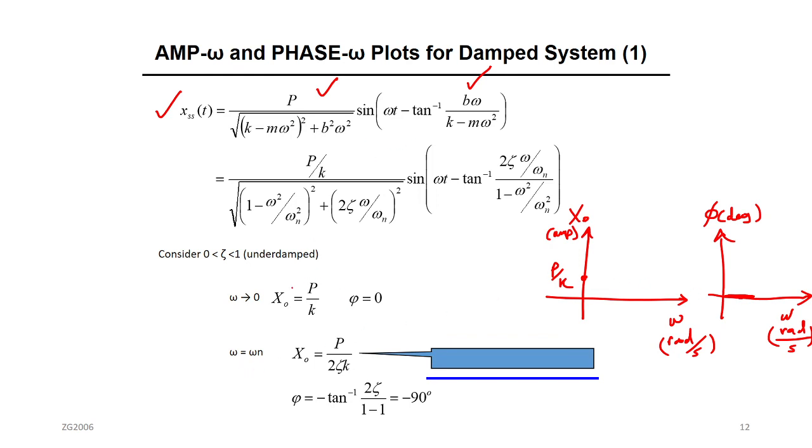When you increase the running frequency, when you increase omega for low frequency, you will have the same thing. You will have positive magnitude, similar to this one. So the magnitude will increase until, I will use this one as it is better for analysis, because we're going to compare it directly to omega n. When you reach omega n, you will have a high magnitude now.